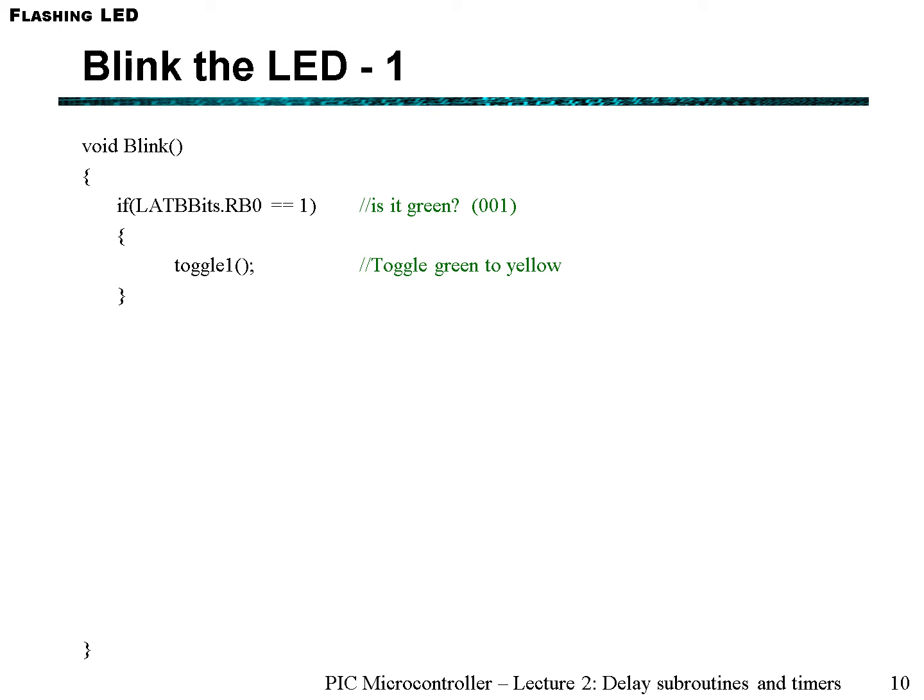So let's look at our C code. So let's say we have a function called blink, so void blink. So that's the function called blinking, and we're checking is the bit high. So we're trying to check if it's green. So the 3 bits between bits 0 to 2 is 001. Now, since only one of the bits can be activated at a time to indicate which state it is in, we don't need to check all 3 bits. We just need to check the relevant bit. So in our case, we just have to check whether the green bit is on.